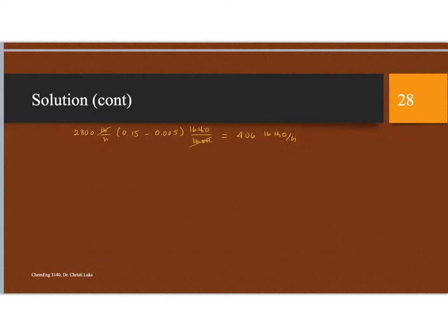The solid is just going to heat up to that exiting temperature, and the water that did not vaporize will heat up to that exiting temperature. So the components of my energy balance, or my heat duty, are going to be, so first the solid will heat up from 80 to 125 degrees Fahrenheit, and I can estimate that Q as the heat capacity for the solid times that delta T.